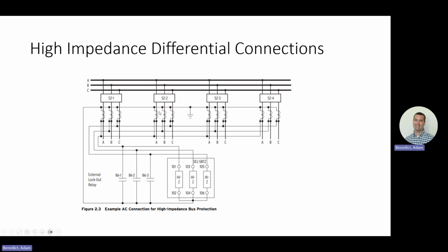But when it comes to our design, all these cables, since they're summed here, they all need to be the same length. So usually what you see, let's see if I can get a pen. Right about here, you would see a junction box. These relays would be wired to this junction box, this one there, etc., down the line.